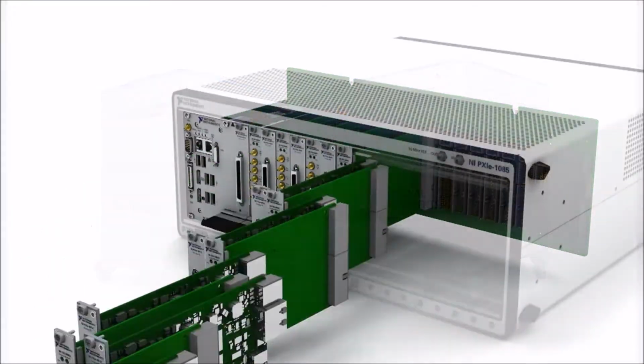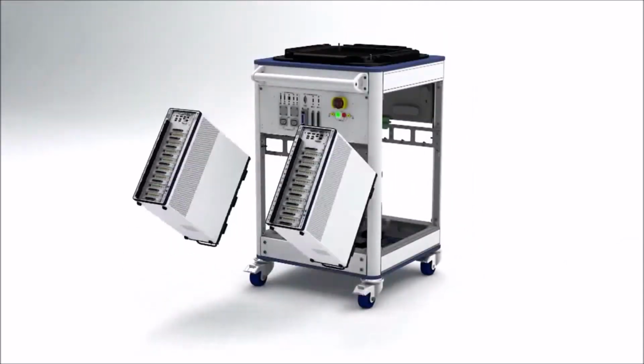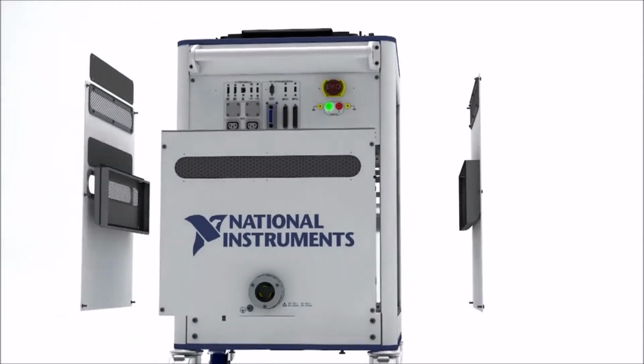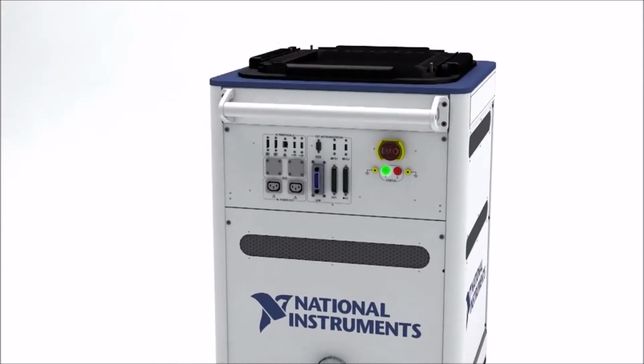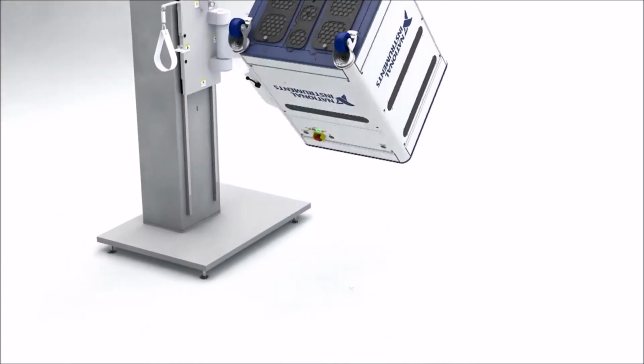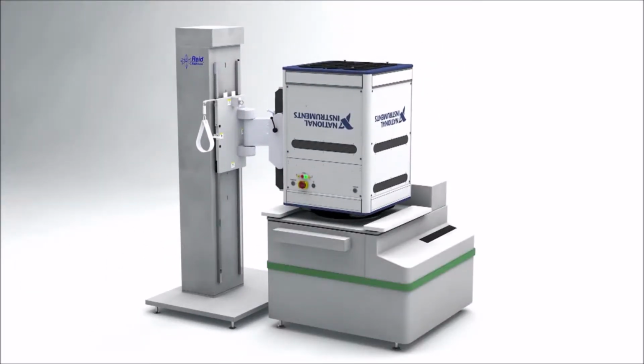So in this video, you can see that a T2 is being created. There's PXI instrumentation inside the test head, in this case 2 chassis full of instruments. The cables are connected to the top of the test head, pogo pins at the top. Load board then gets set down on top of the tester. Then you can pick it up with a manipulator and set it down into either a prober or connect it to a handler of some kind.